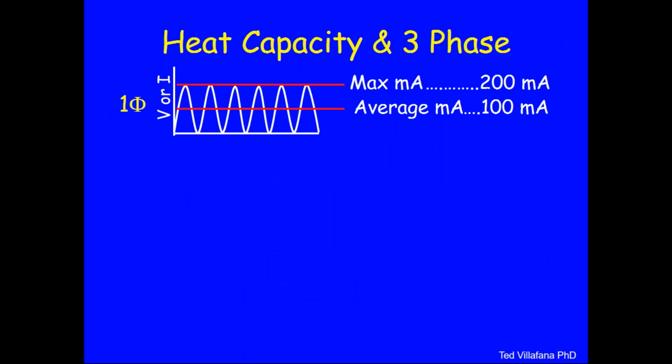But now I'm going to give you a third advantage. I've mentioned only 2 so far. There is 3. And that is the heat capacity of a system. Remember we mentioned and showed you that three-phase allows you to rotate the anodes 3 times faster, and we compared the heat rating charts and showed that there was a significant improvement in heat capacity. Well, that improvement was because you went faster on the anode rotation, but now also what I'm about to present.